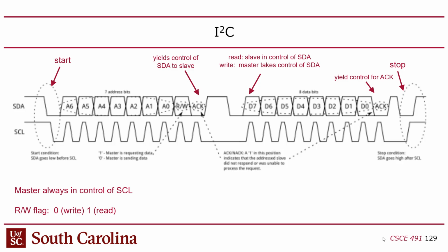The only exception to that rule is here, because you break the rule at the beginning, and this is what indicates to the bus that we're starting a transaction, right? Because the data falls first. You drop the data before you drop the clock. That is an extraordinary event because you're not supposed to ever do that, right? But that's what triggers the starting condition. And then likewise at the end, the stop.